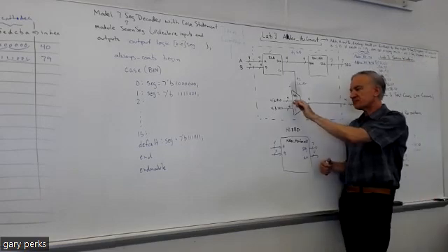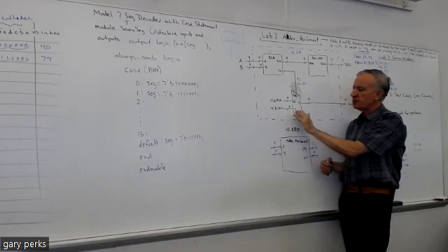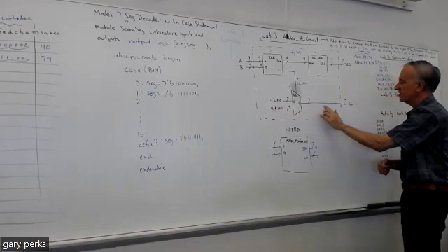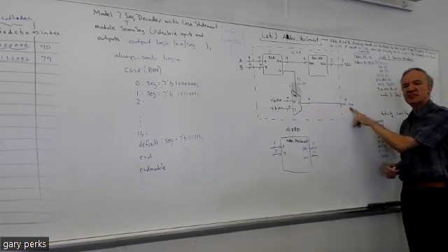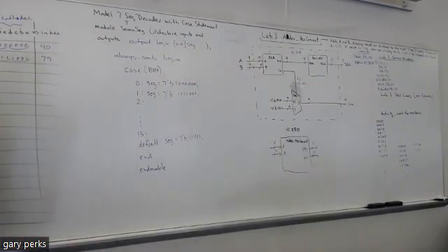But you see here, the 0 input of the mux is connected to this 4-bit data, 1, 1, 1, 0. And this input 1 is connected to 4 bits all equal to 1. And then look where the output of the mux goes. It goes to AN. What's AN again? Anode. Right? It's this bit right here. So what is that anode controlling? Say it again. 7 segments. Right, it's the common anode of the 7-segment display.